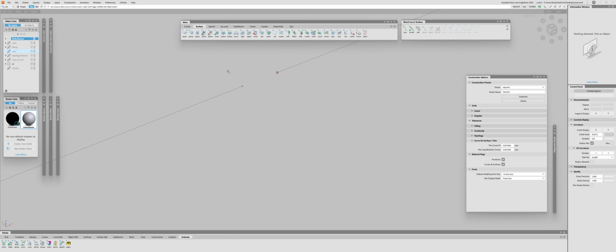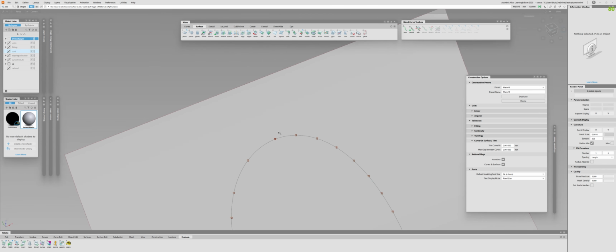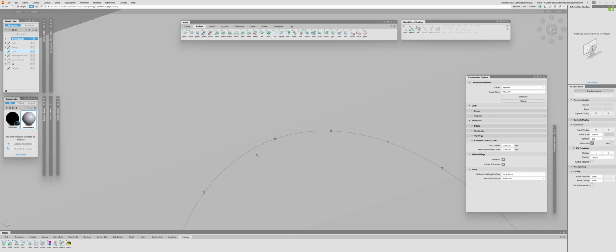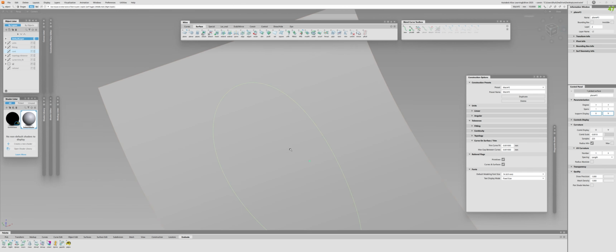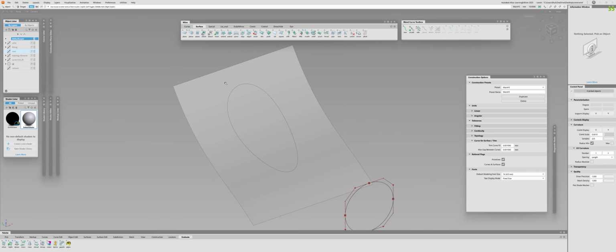It will trim it, yes, but next time when you try to build from or to this trimmed edge, a transitional surface or fillet or whatever, you will have a hard time, a lot of spans, probably no curvature, and that's only because of this small gap which Alias closed by itself, because you have a pretty loose tolerance in the max gap between curves. So a good rule of thumb is to keep it tight, so you don't encounter these problems.